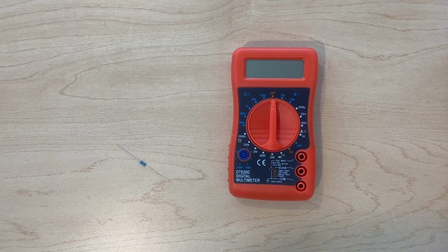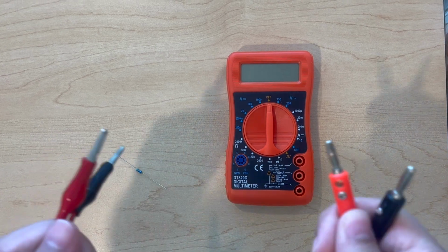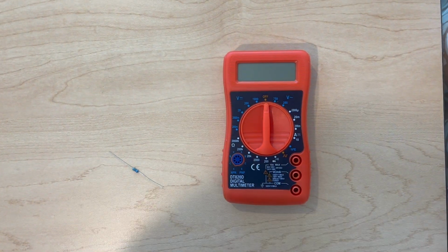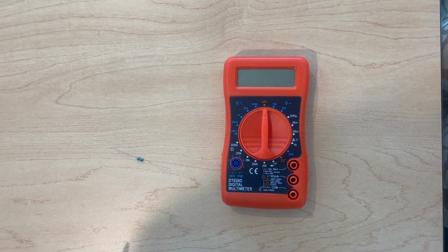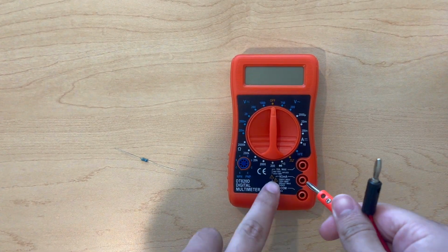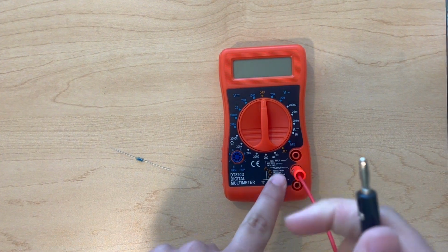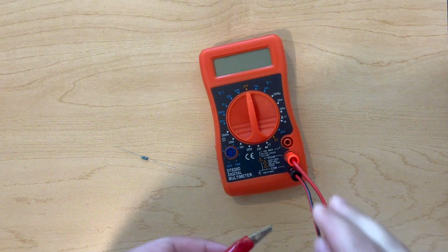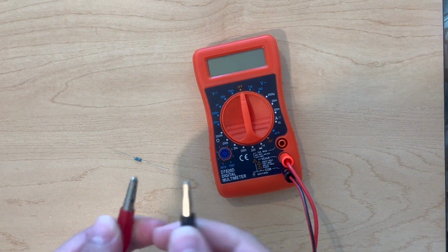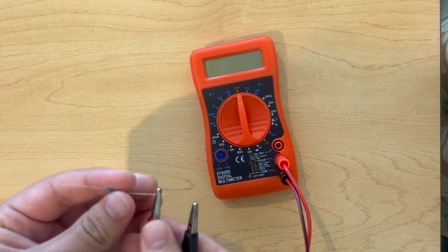So here we have the multimeter, the wires with the multimeter, and that 470 ohm resistor from earlier. So first you're going to take the red wire and you're going to plug it into the one that has the ohm symbol for resistance. Then you'll take the black one and put it in the ground position. Then you're going to take the 2 grippers and ever so carefully connect the resistor to the power and the ground.